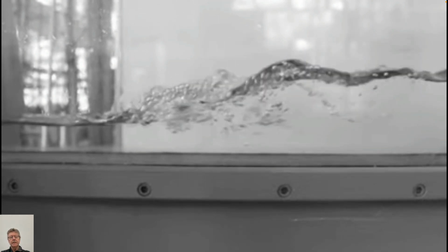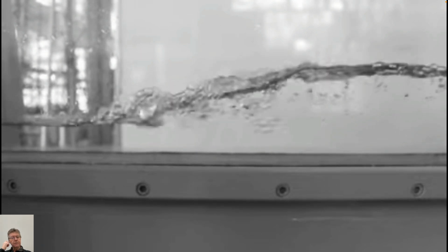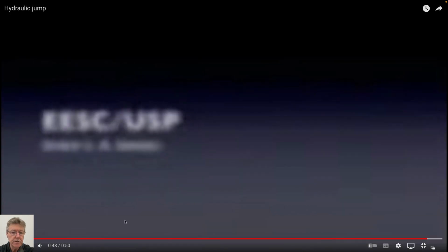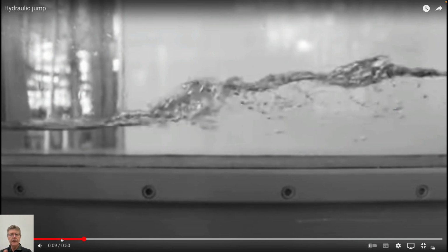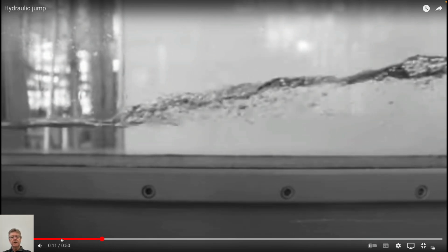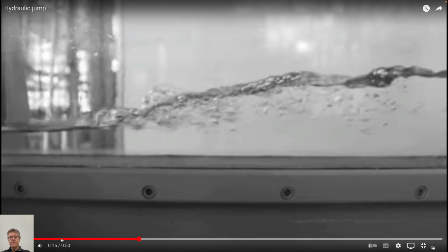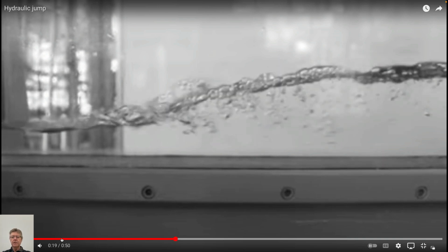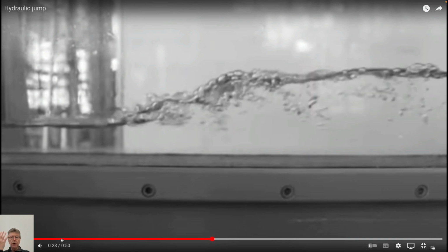But the issue is that you have this free variable in terms of the free surface, and from continuity, you know that if you draw a vertical line anywhere along this, the same volumetric flow rate, Q, has to be going across it. The downstream portion has a deeper depth, and so the cross-sectional area is larger, so the velocity for the same flow rate has to be slower.